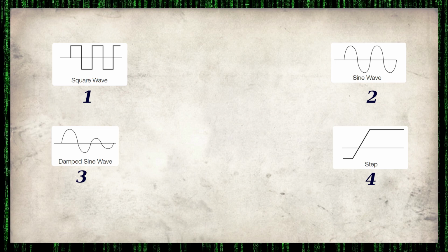You as the engineer can decide that if it's somewhere between 4 and 5 volts, we accept it as being a 1. So in this case, it starts off with a 1, and then it drops down, and it's fairly close to being a 1, and we'll accept that as a 1.